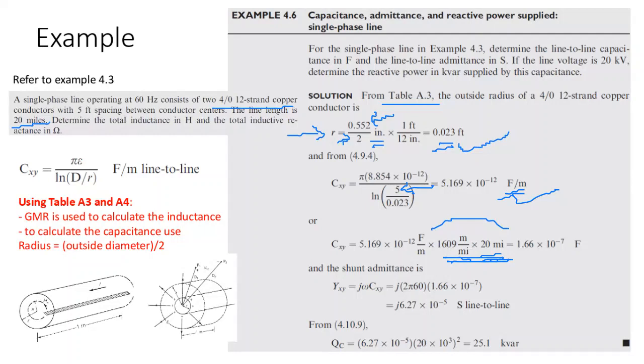Then you will read this and determine what to do, when you read the voltage profile of the system and the transmission flows. I'm talking about load flow software, for example. But you need to prepare the R, the X, the C. That's what you put for the transmission line, and the inductance you put in per unit. All this is done offline. So you already know the distance between one city and another city, with the transmission line.